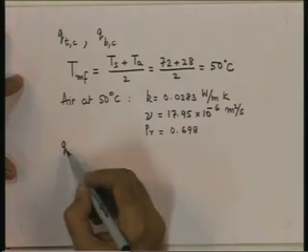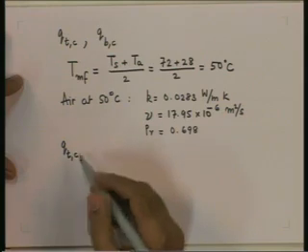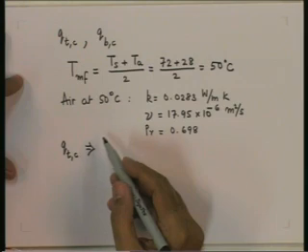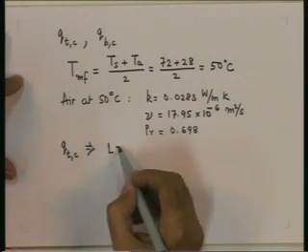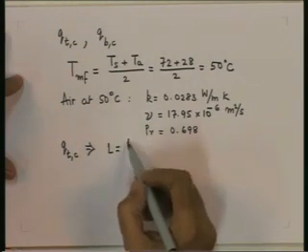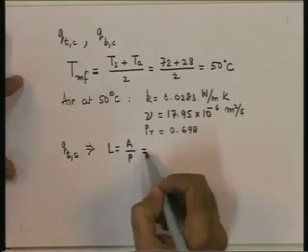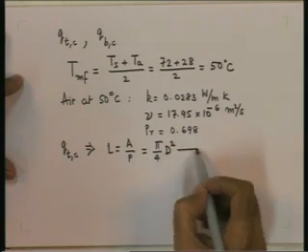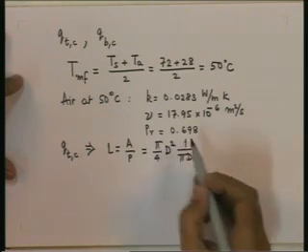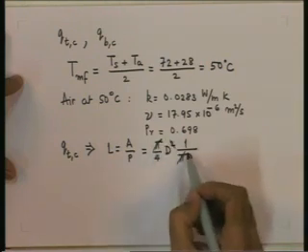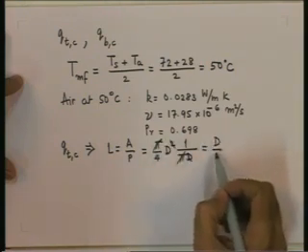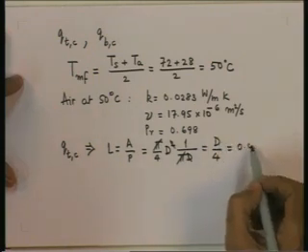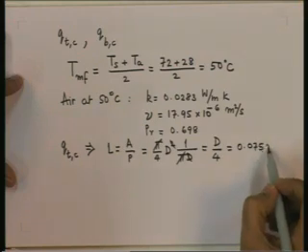Now for determining the heat transfer from the top by natural convection, it's a circular plate, the definition of L here is area by perimeter. Area is pi by 4 d squared, perimeter is pi d. So we get diameter by 4. The characteristic length here is 0.075 meter.